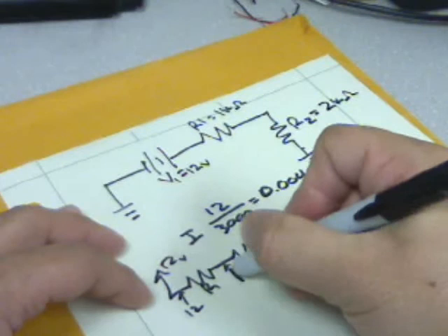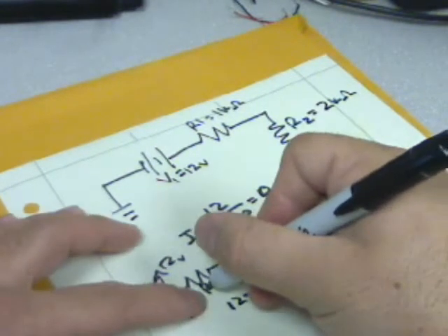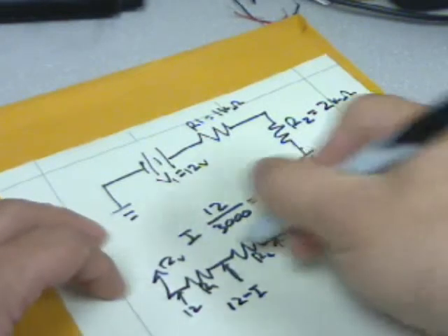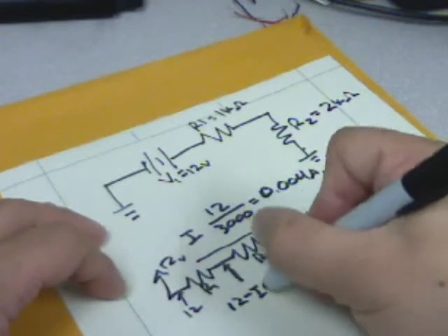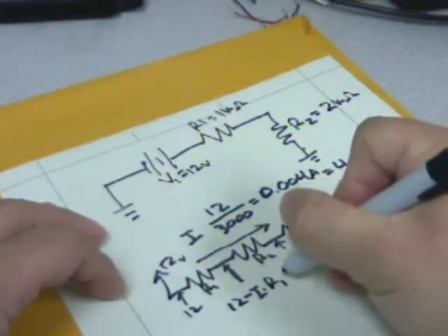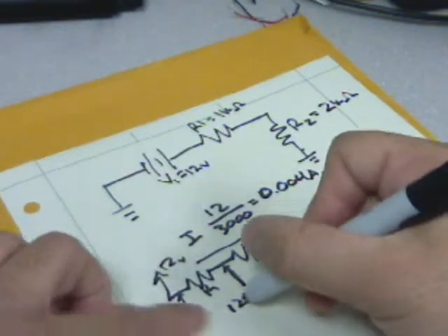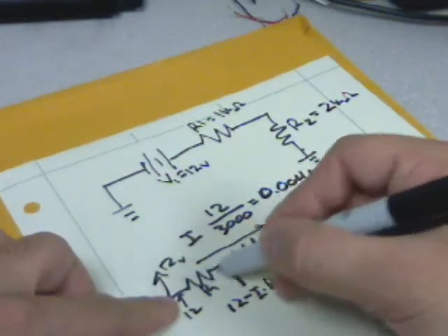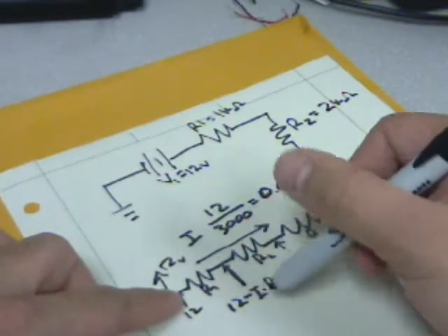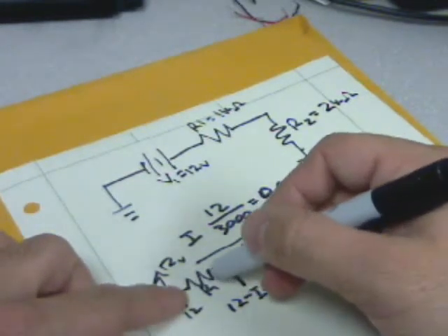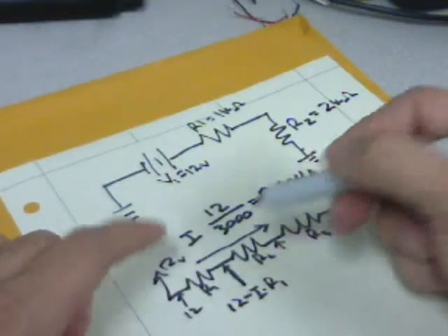If we put values on R1, R2 and R3, we can actually tell what the voltage is going to be right here. It's just going to be 12 minus the current in this circuit times R1. There's only one current, since it's just a series circuit. That is what this voltage would be: 12 minus whatever volts got dropped across here. That's what we mean by a voltage drop: because current is flowing across this resistor, we have a potential difference between this point and this point.